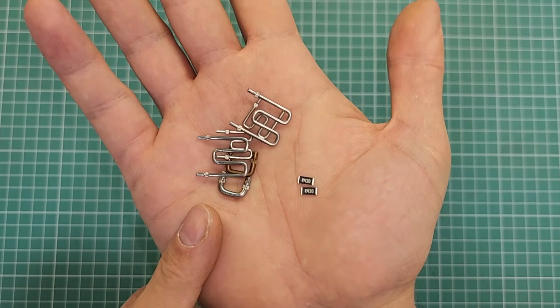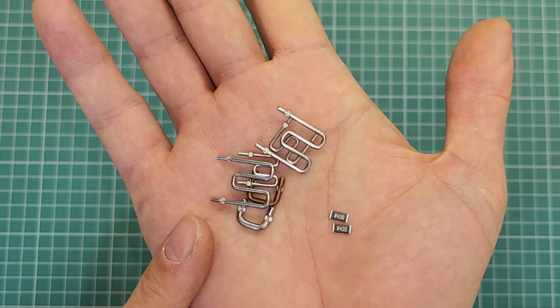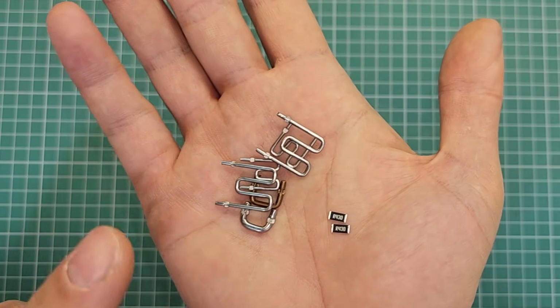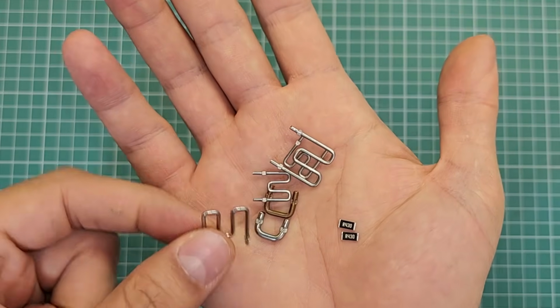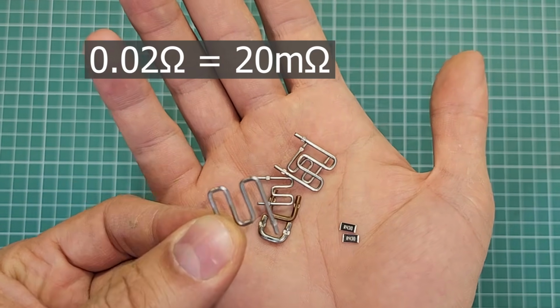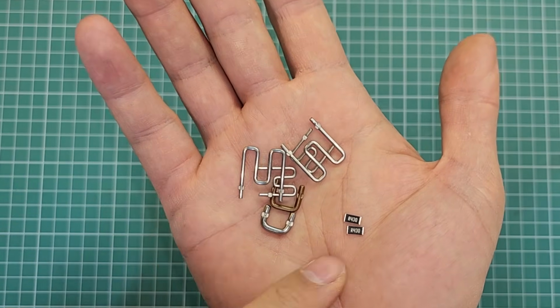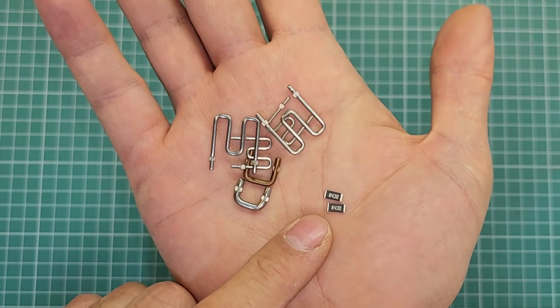These are shunt resistors. They are used to measure current. The distinguishing feature of shunt resistors is their low resistance value and high current tolerance. For example, this one is a 0.02 ohm 10 ampere shunt resistor. Also, this one is an SMD 0.43 ohm shunt resistor.